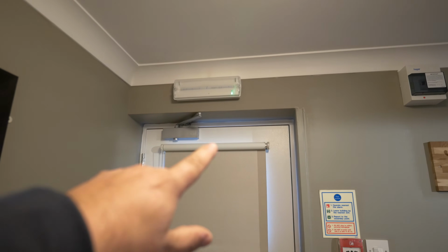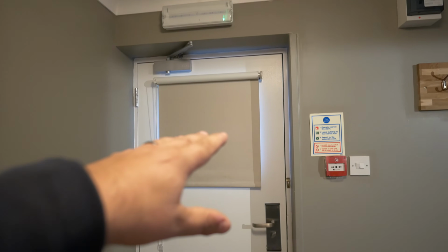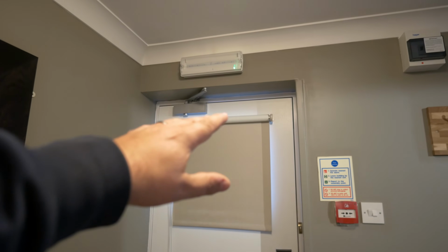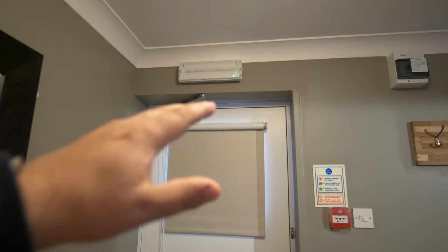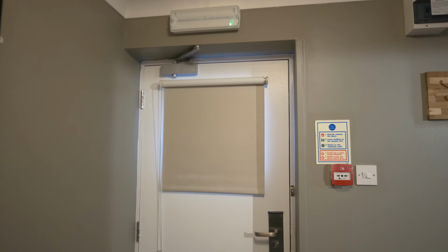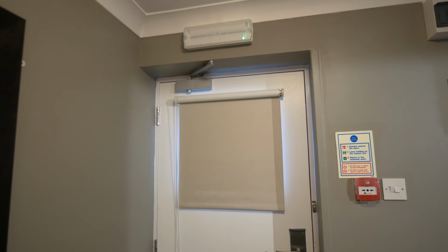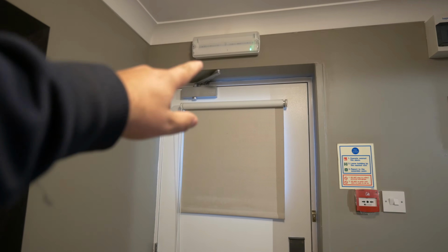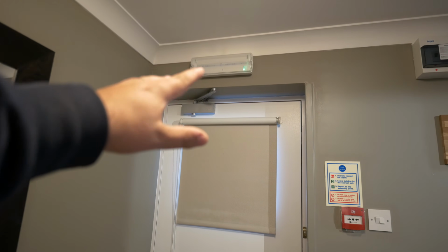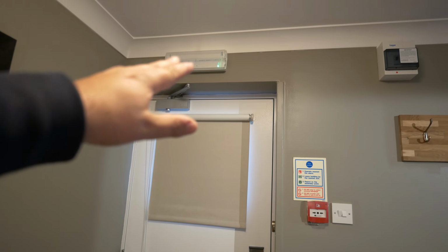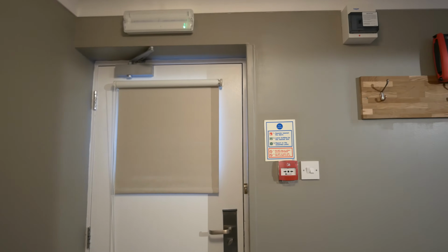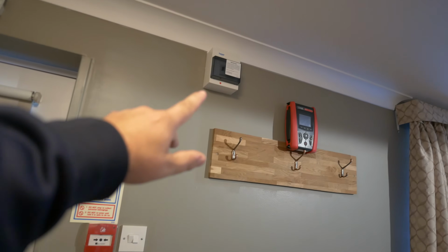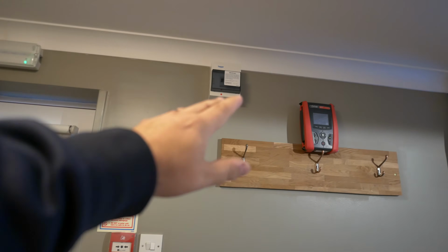There is also an emergency light above the exit point to this accommodation, and we will be testing the fixed wiring up to that, but I'm not carrying out emergency light testing during the course of this inspection, so we won't be duration testing it, but we will be making sure it's got an adequate and safe supply. So again, documenting that in the certificate is super important, to make sure you're stating clearly what you are actually covering.